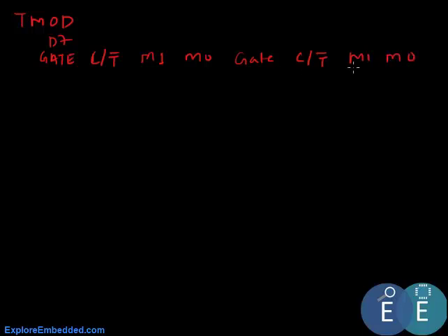If you remember the discussion on timers, to configure the timers we have a register called TMOD, and the last bit is gate, so this is D7. D6 is C/T bar, then this is M1 and M0, so this is mode. These 4 bits are for timer 1, and the next 4 bits are for timer 0, and for serial communication we are using timer 1, so we can make these 4 bits 0. Now we want the timer to be in auto reload mode.